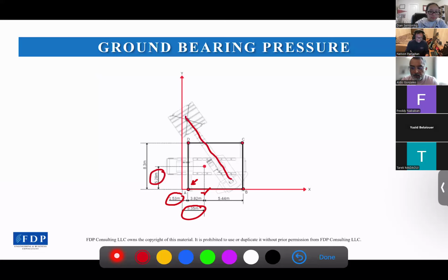That's because in this job I actually checked the COG at each degree of slewing angle, but in the drawing we show only one slewing angle, just to avoid confusion. I copied this picture from the actual drawing. So yeah, there is the COG.